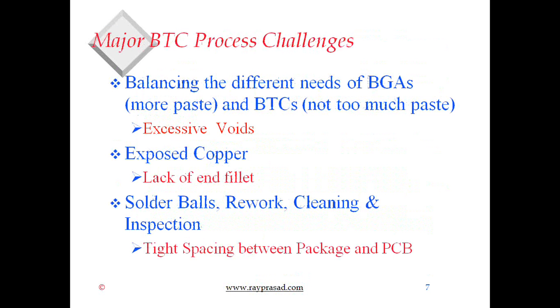Some of the major challenges, on slide 7, are that you have different needs for these different components. As an example, this is not a seminar about BGA, but in general you have heard of head-in-pillow and those kinds of issues. There are a lot of reasons and ways to address those, but in general I think you are better off with more paste.